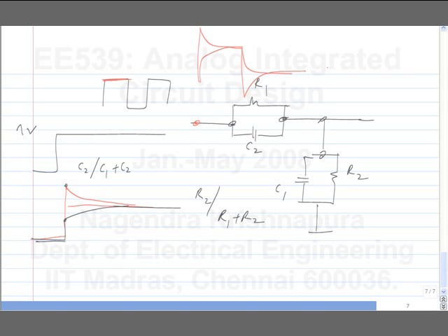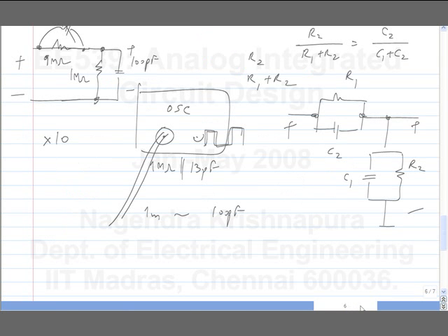So anyway, this is all distracted from what we were discussing initially, that if you have two node voltages to be identical, you can connect them together without affecting the circuit. And there's a very easy way to verify this. You write some circuit equations, the network equations in a general format, like KCL equation in terms of the node voltages. And if two node voltages are the same, you can connect them together. No extra current flows through that. You'll be able to formally prove that this is the case. Okay.